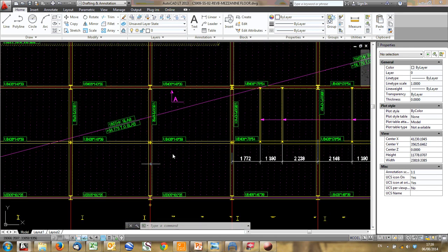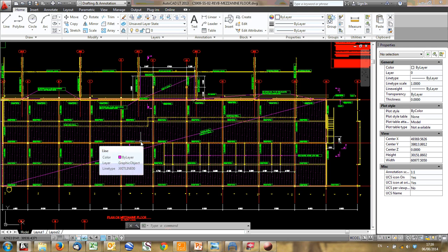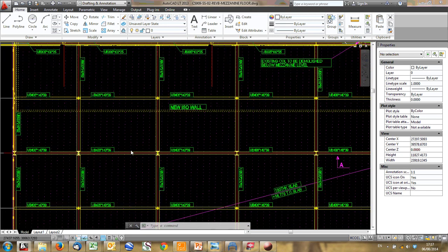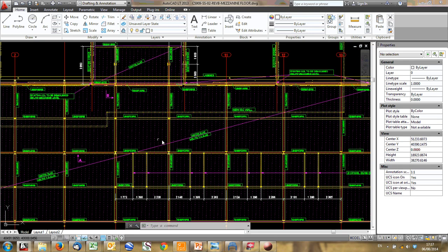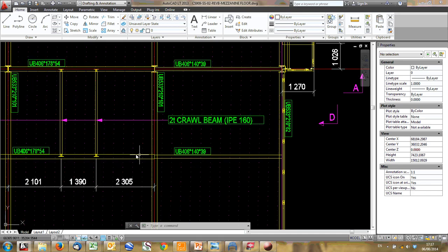We've got beams, etc. supporting the composite floor. For this example, we're going to assume that these beams are not composite. They're just standard beams supporting the floor. And we can now do a load rundown in a very similar way as we might do with a truss. These beams, as I said, are simply supported.